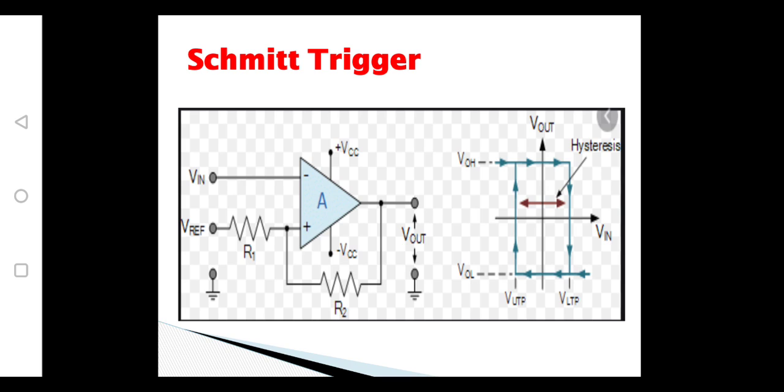The same minus is fed back towards the positive terminal of the op amp. So when input is slightly more positive than V reference, output is driven into minus V saturation. Similarly, when input becomes more negative than minus V reference, it is driven into plus V saturation. So the output always varies between only two values, either plus V sat or minus V sat.